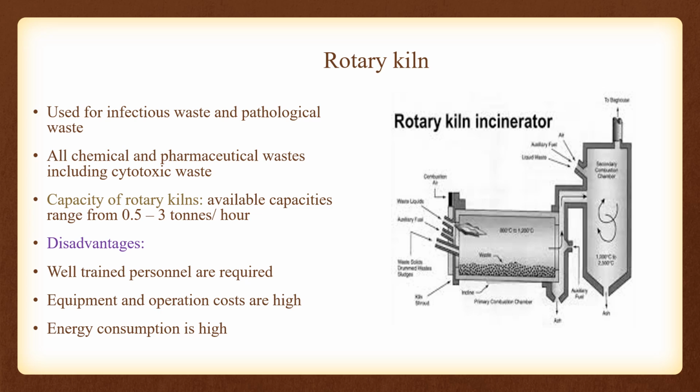And regarding that, what are the disadvantages of the rotary kilns? There should be well-trained personnel. Equipment and operation costs are high, and energy consumption is also high. Highly corrosive waste and byproducts damage the refractory lining of the kiln. So these are the defects of the rotary kiln.